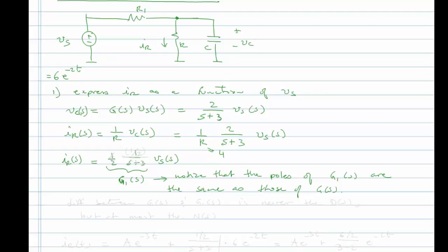And it turns out that for all of those, the transfer function will always have the same poles. So what's expedient is that if all you're being asked to find for a given system is the functional form of the natural response, you can write any transfer function and find the poles of that transfer function, and they'll be the same poles for all of the transfer functions. And from there, of course, you can write the e to the st terms in your natural response.